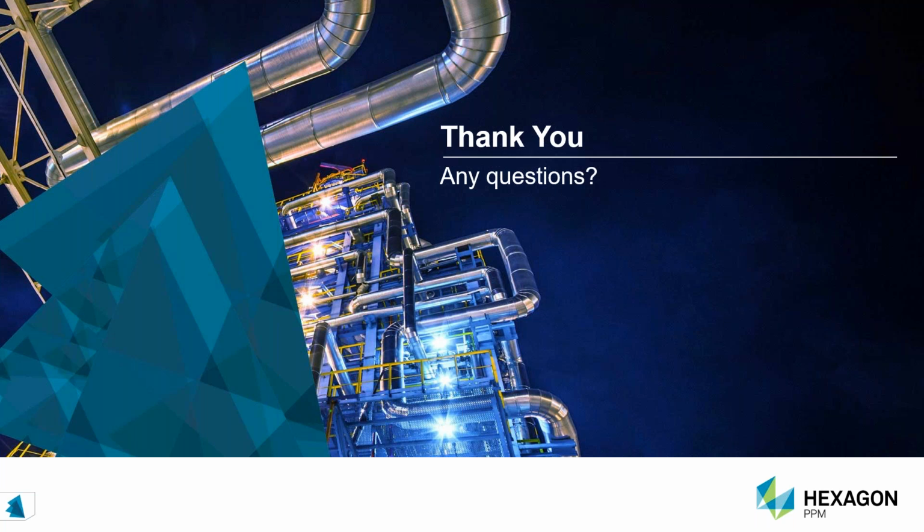There's also a question here about using data from other solutions, so other third-party scanning solutions, in particular reference to FLS files. So yes, you can import FLS files directly into Register 360. You can push those through into Jetstream and LGS, and you can then use that data alongside the CADWorx platform. So we try and be as open as possible in terms of the infrastructure, and we also support import and export of recap files as well, so that you can use those alongside. So there's lots of different ways that you can get the data.